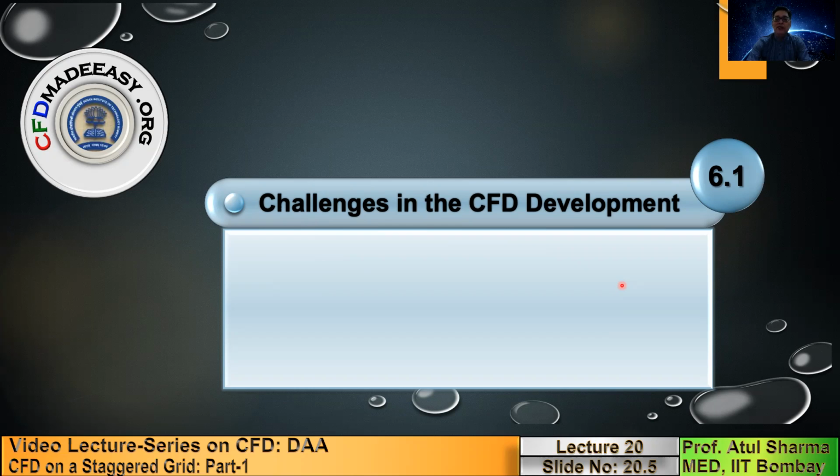So one of the challenges in CFD development has been the nonlinearity, which corresponds to the advection term. And when you move from computational heat transfer to computational fluid dynamics, the additional conservation law that you encounter is the mass conservation law. This lecture series is presented for an incompressible flow.